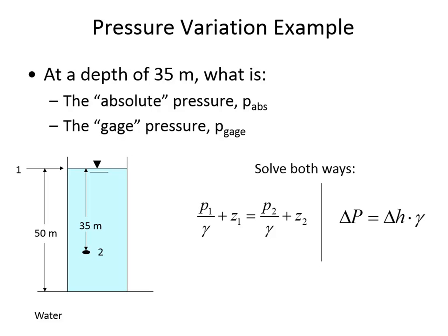Well, in this approach, what we're doing is we have Z1, so the elevation at 1. We're letting the bottom of the tank be our elevation datum. And so location 1 has 35 meters of elevation and location 2 has 15. And so I actually substituted in the actual elevation of 50 and 15 because this is all on the basis of elevation above the datum. But in the second method is where I use the 35. I don't know if that answers your question.